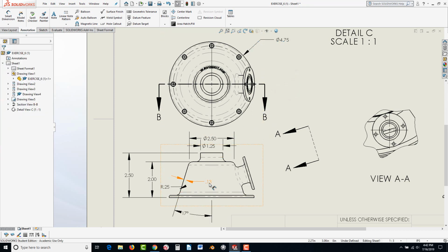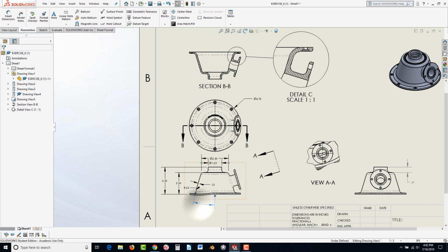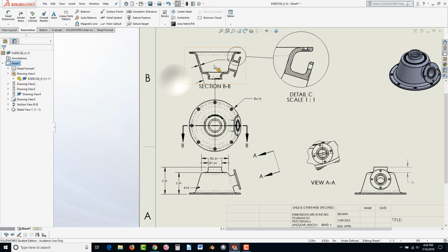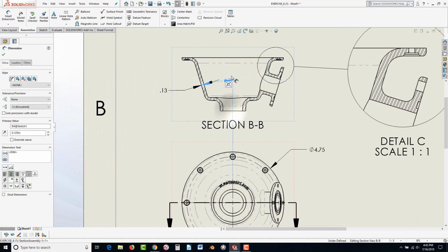Now I'm going to go ahead and I want these two to be up top. So I'm going to zoom out. I'm going to Control, select those two. Release Control, then hold Shift, and then drag with your mouse button depressed and drag them to the center. Don't drag them where you want them. Drag them to the center of the view. Release, and now those come in there. Now click somewhere off or hit Escape. And now you can move this over here and the 17 degrees. Let's move that up here.